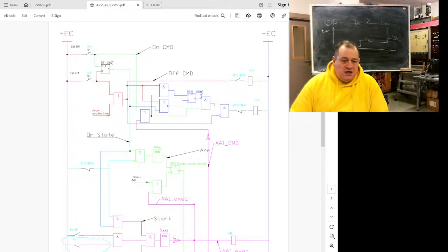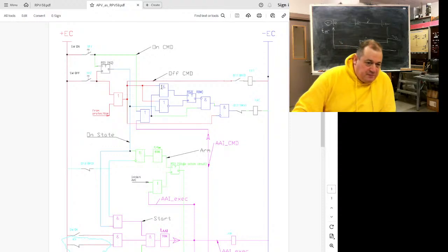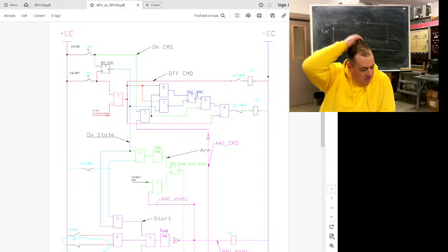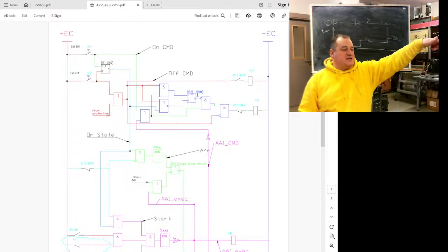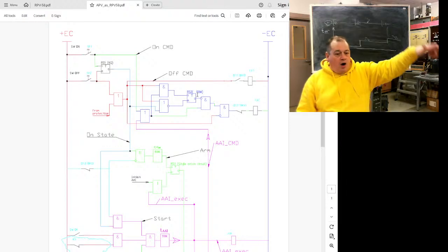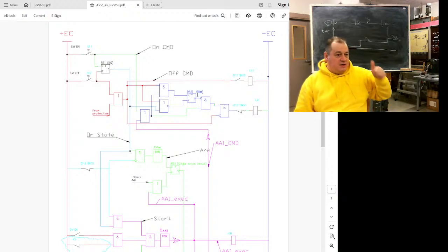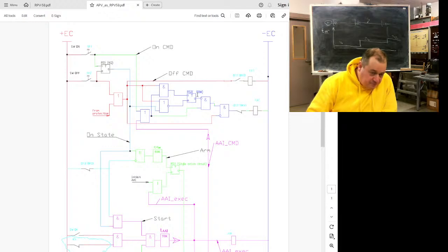And this logic ensures what? The on signal will go through only once, and a second one can be sent only after disconnection. It's a logic preventing auto reclosings, multiple reclosings, or multiple on-off when the on signal is held, when the switch is pushed or the remote dispatch system keeps the signal.